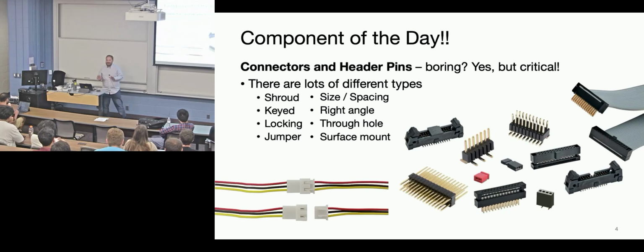Why did that happen? At the time she was just using normal header pins like this to connect her batteries, and this big beefy battery. She was a little nervous and she put it in backwards. So now you took power and shorted it directly to the ground and something caught on fire.